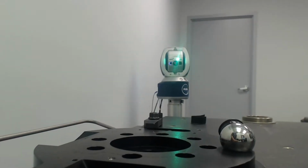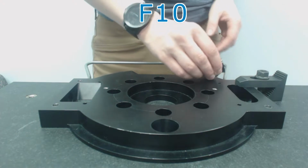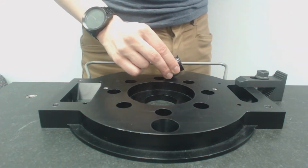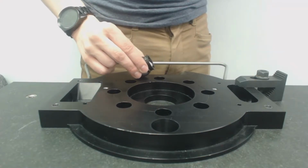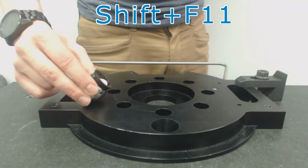If you are using a tracker, you can use the keyboard shortcuts F9, F10, and F11 to start or pause measuring, accept or discard last respectively. You can also discard all the points by pressing Shift and F11.